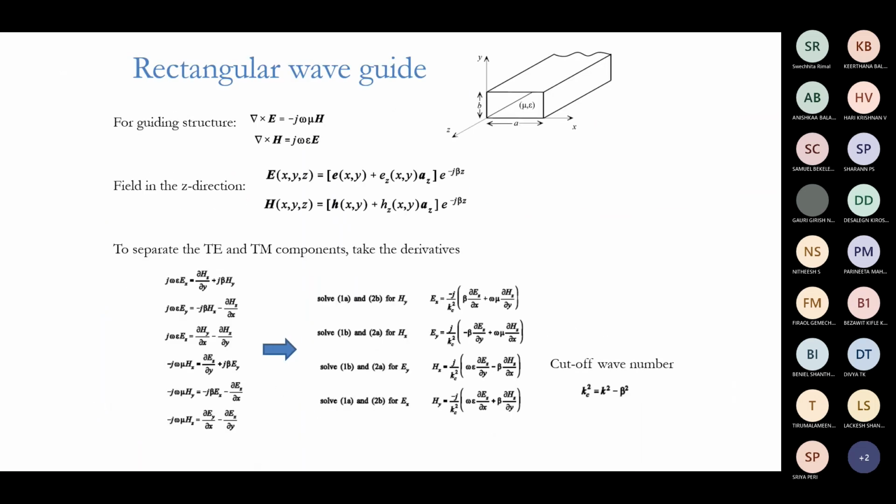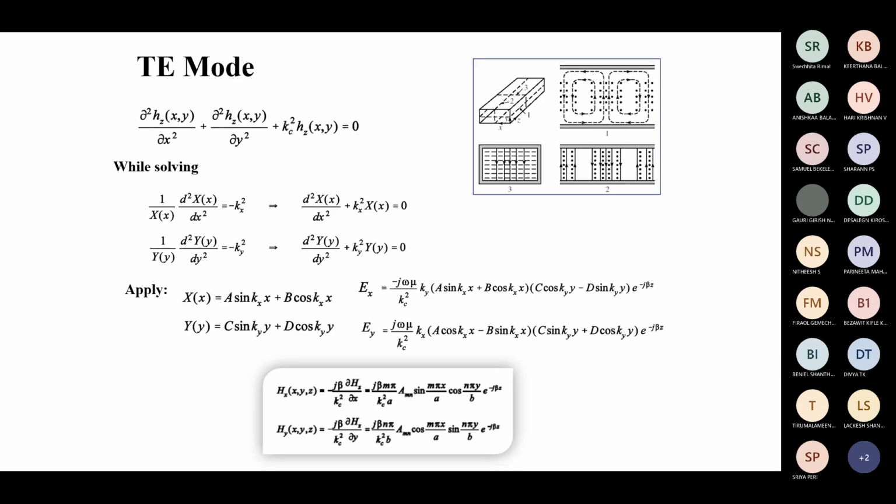For this, we have to apply Maxwell's equations. We have to self-consistently solve the equations. It is not a big deal. Simply differentiate one equation and substitute it into the other. Then you will get a second derivative of the vector. Obviously, this gives a second-order equation that has two solutions: one is the positive-going and the other is the reverse-going signal. That is the wave equation, and to that wave equation we apply the boundary conditions.